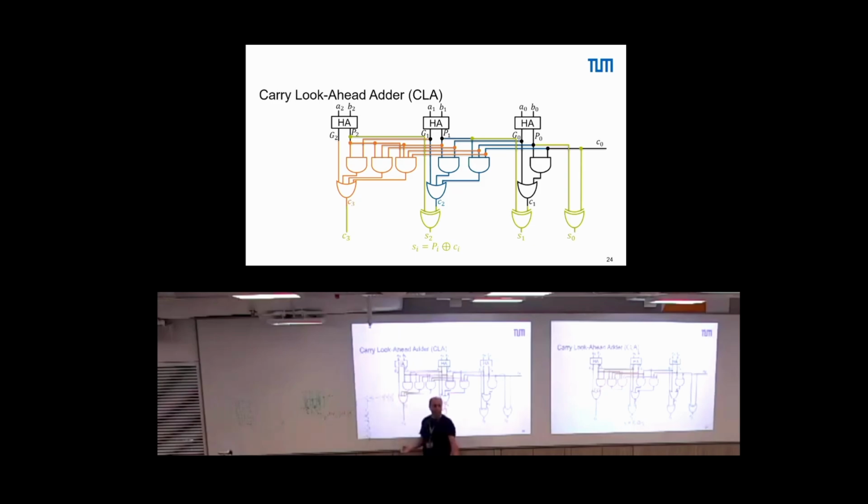If you put this into 2 AND gates, then you have effectively 1 NAND gate with 3, another with the same size, then an inverter for each, probably, depends on how you precisely implement, and then another NAND gate. So more area, more chances to have a fault.